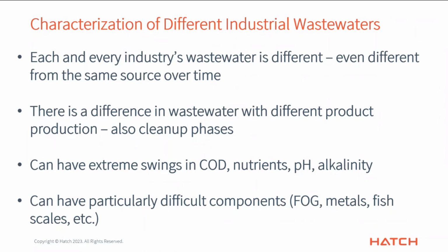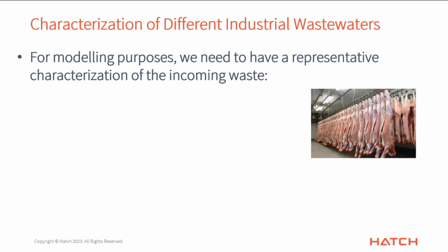I threw fish scales on here. That's another project that I had where the client was telling me all about the fish processing facility, how fish scales are really difficult to deal with in that particular activated sludge system. The fish scales themselves are slowly biodegradable, so they're hard to treat and they stick to everything, and they are also neutrally buoyant, so they neither floated nor settled out. It was a really interesting story, although difficult for them to have to deal with.